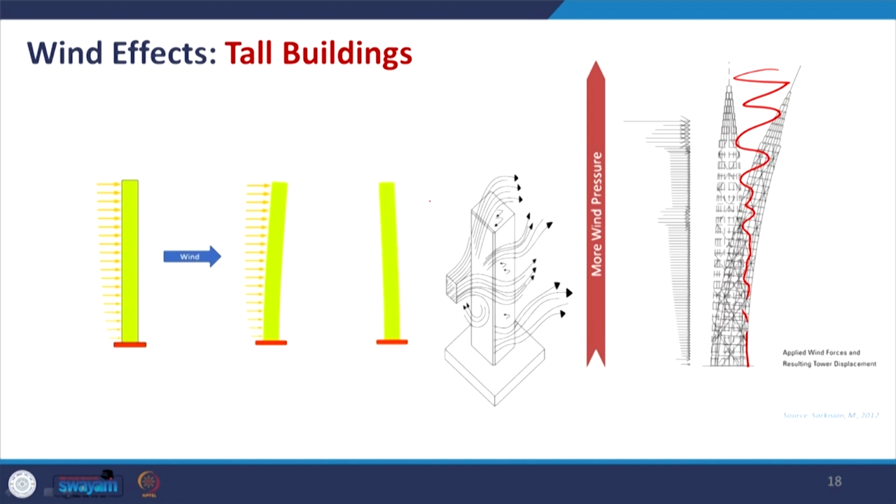That is why, when we discuss high-rise structures in upcoming lectures, we will touch this again, where we will see different kinds of core structures and tube structures that help protect the high-rise against lateral load, especially from wind. For them, earthquake will definitely play a different role, but along with that, with the increase in height, wind is one of the major factors to be considered for high-rise building design. So, this phenomenon is there.